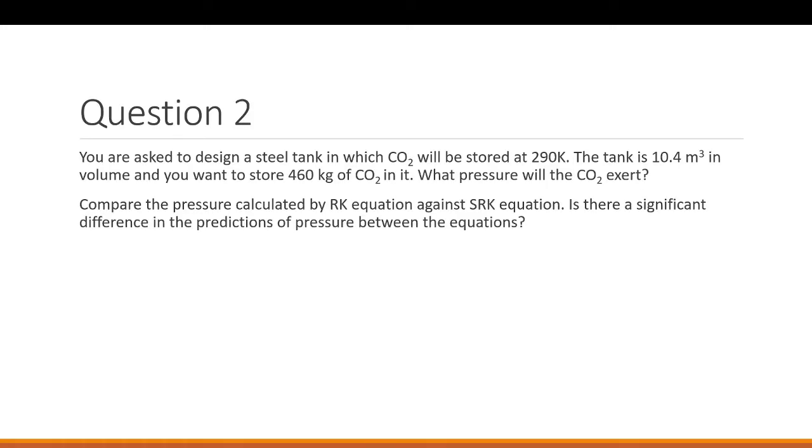Question 2. You are asked to design a steel tank in which CO2 will be stored at 290 Kelvin. The tank is 10.4 meter cube in volume and you want to store 460 kg of CO2 in it. What pressure will the CO2 exert? Compare the pressure calculated by Redlich-Kwong equation against Soave-Redlich-Kwong equation. Is there a significant difference in the predictions of pressure between the equations?